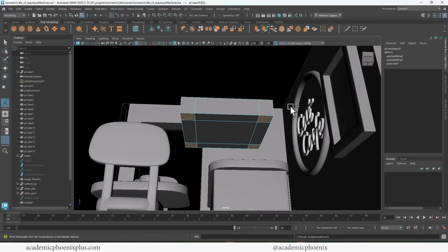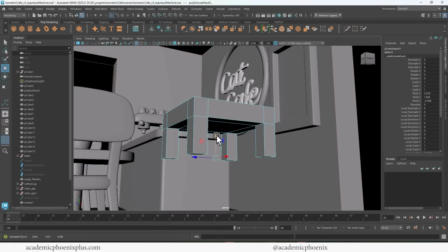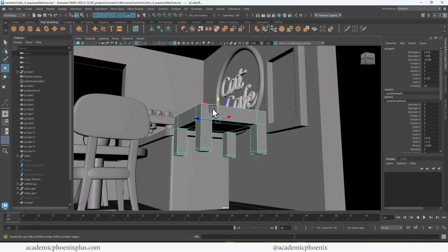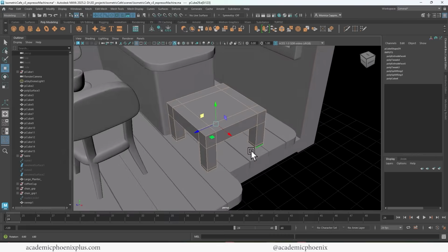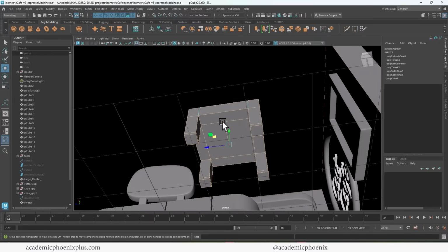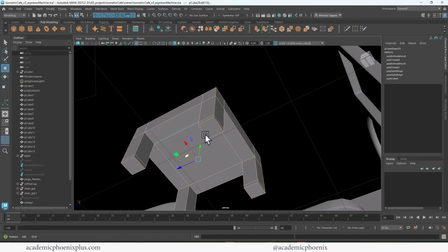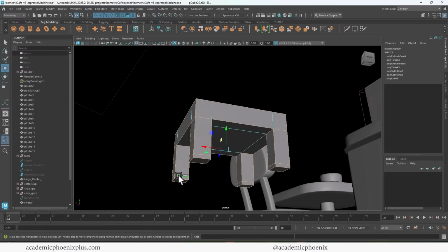So it would have saved me some time if I had done that earlier. So extrude, bring it down, and then extrude again, Control E, bring it down a little. Again, there's a lot of edges here, but let's go ahead and select these edges, and I only want the ones that need to be beveled. So none of these in the center here, and definitely none of these here either. So I'm going to go ahead and deselect those, and also deselect these.